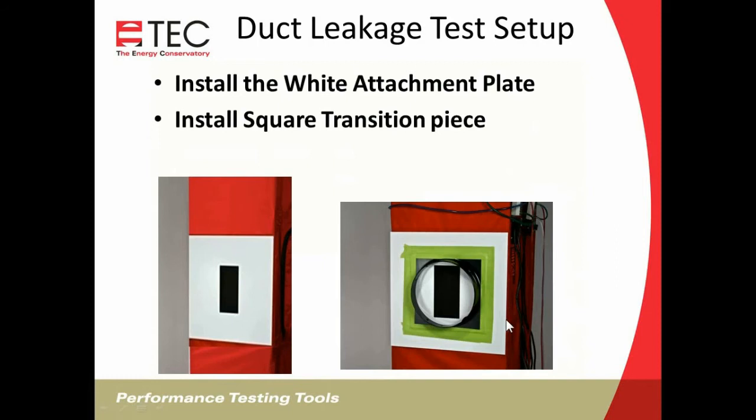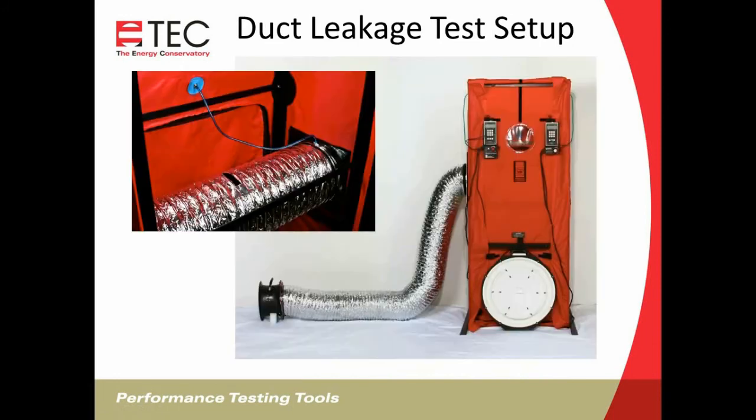And for the duct test leakage setup, next you'll attach that Velcro of the white attachment plate and line up the hole and Velcro that to the side, and you'll attach the square transition piece of your flex duct to that white attachment plate, and then you'll attach the flex duct to that. So now we've got a blower door and a duct blaster with the duct going through the center of it.